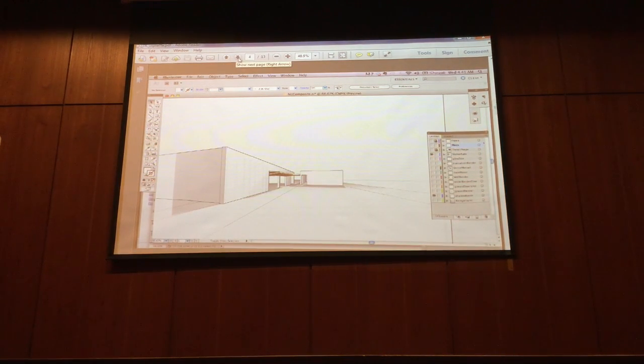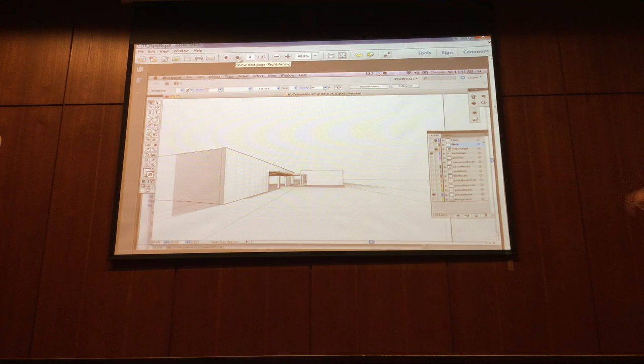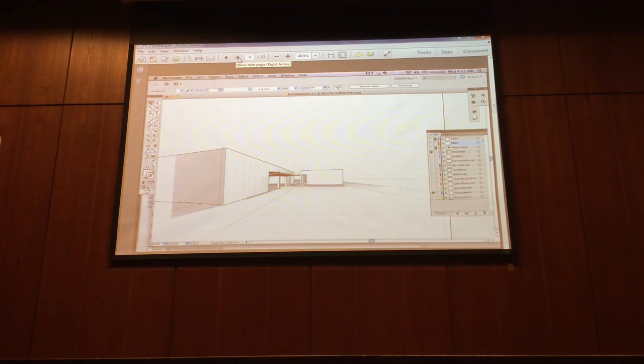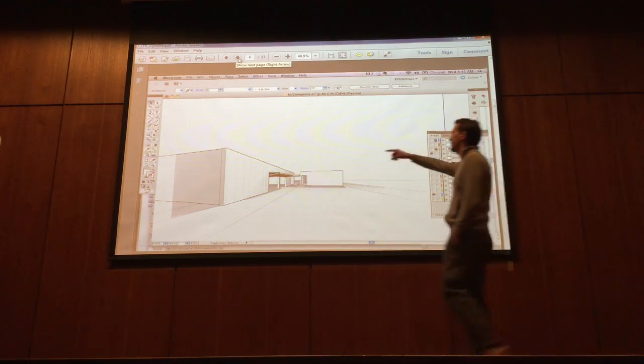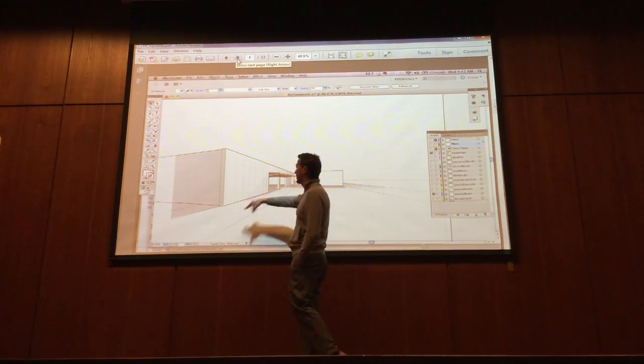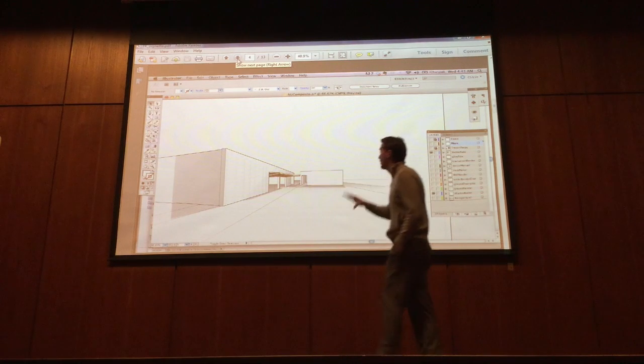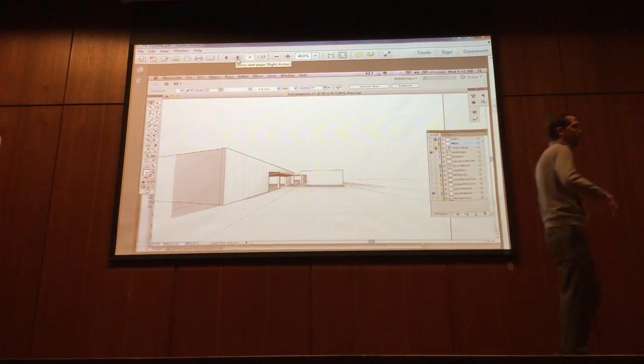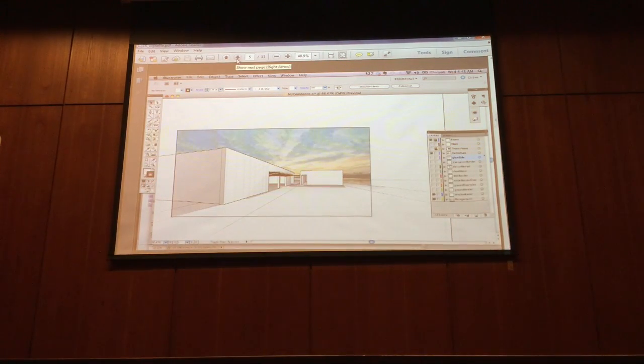It's got all the values. Now it's got some line work from Make2D. I would argue that he may have wanted to do what I would do typically. With Make2D, I might edit all that line work, join all this stuff together, and put it on separate layers in Rhino itself, because it's easier to manipulate the geometry there than it is here.